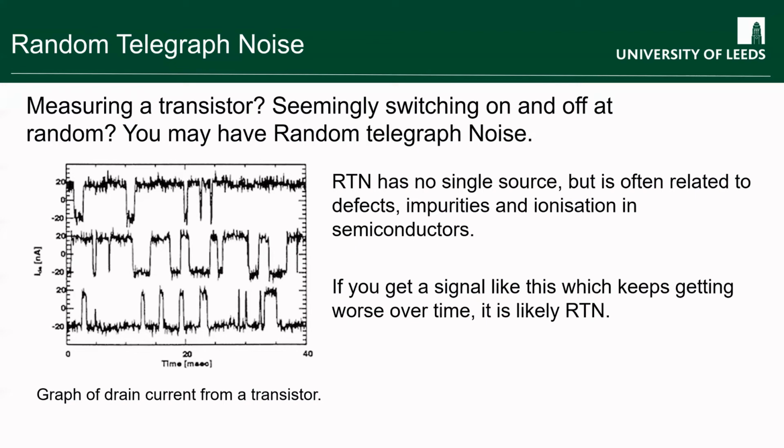And again, to fix it, you might be able to just simply improve the measurement. Alternatively, you might be able to look at, say, histogramming your output and recognizing the bistable state, and that might help. You can either decide which state you want to measure, or you can at least understand what's going on. So these are all things to be thinking about if you're seeing a noisy signal. The first thing when you're doing the experiment is trying to evaluate whether you're seeing more noise than you might reasonably expect. And then if you are, you want to be looking at ways in which you can identify what's causing it, and that will be the thing that will let you fix it.